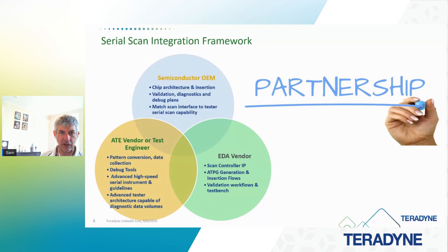And then it's also very important today. Another thing that's happening with scan is we see a lot of data collection happening in terms of scan map failures. Sometimes this is used for advanced binning workflows. Sometimes this is used for advanced fault analysis and debug workflows. But the tester architecture has to support a lot of data passing. And our current generation UltraFlex Plus platform has a tremendous bandwidth at the tester. And so that's something that's been helpful in that regard.